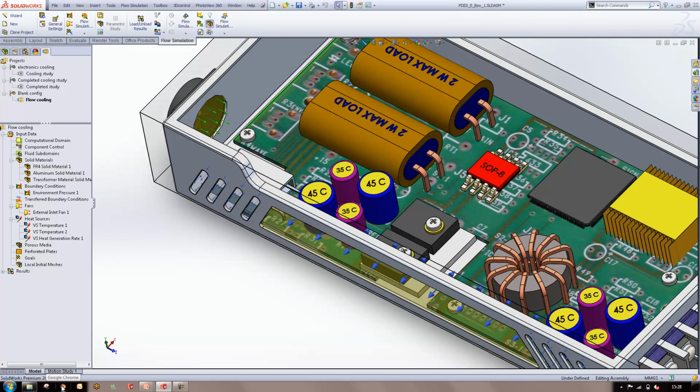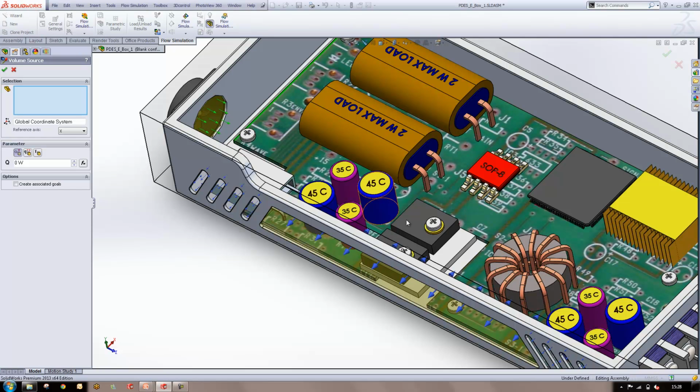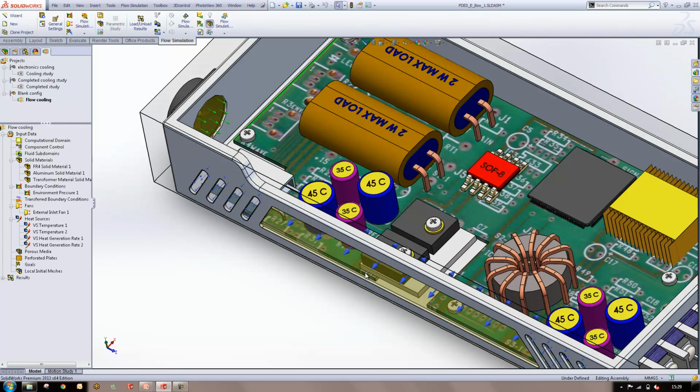Again, very much like the FEA analysis tools, we can just pick off our geometry and apply each of our individual settings to each of our individual components with great ease, because it's already there and on our screen and ready to go. So I'm just going to stick 0.5 watts on there, etc, etc. I don't need to go around and do everything. We'll see that later on.